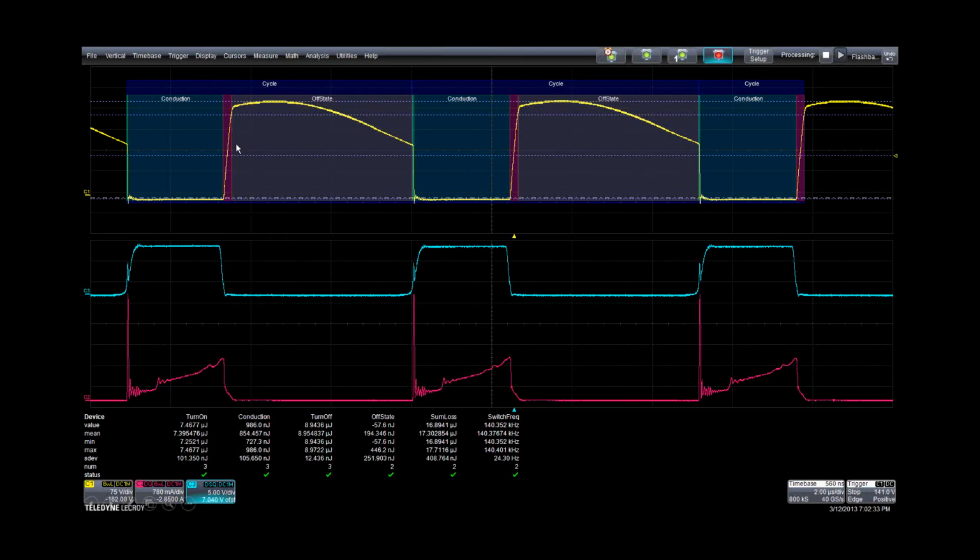So here we're looking at, again, the same kind of thing we were before. We have our voltage up here, our current down here, and you can see it goes through all the states of the switching cycle. But now I'm probing another piece here. This is in channel 3, the gate drive signal. So this is the signal that's being fed from the PWM controller to the gate, and when it goes high, it's going to close the transistor, and we can see then it's low voltage and conducting current. And the way that it's going to supply more power to the load is to use a wider pulse. And if you need less power, it's going to use a narrower pulse.